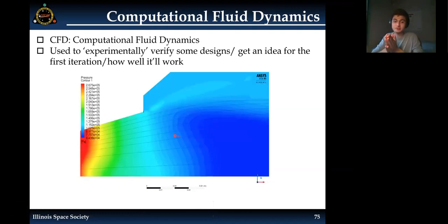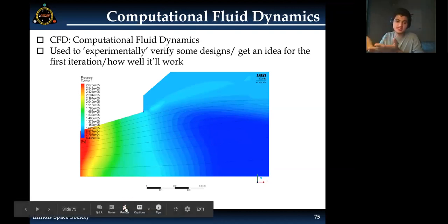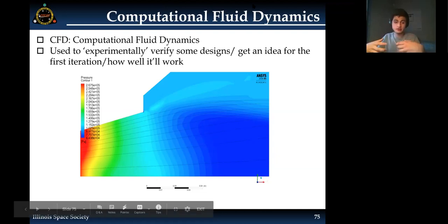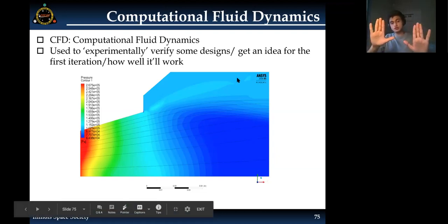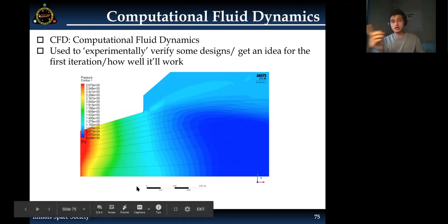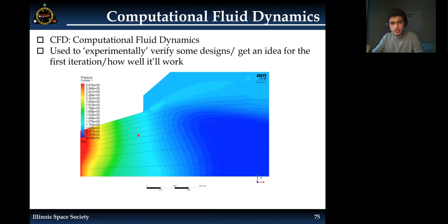Essentially, what we're trying to do is make sure that the flow is perfectly expanded, because that's when we know that the nozzle is working correctly. So what I've done here is zoom into this CFD that I did of our own nozzle, and I'm showing you a cross section of how the pressure gradient across the exit looks. As you can see, the pressure on the right is just about equal to the pressure on the left. It looks bluer, but if you look at the scale, it's close enough for us to assume that it's nearly perfectly expanded, and it gives us a good understanding of that.